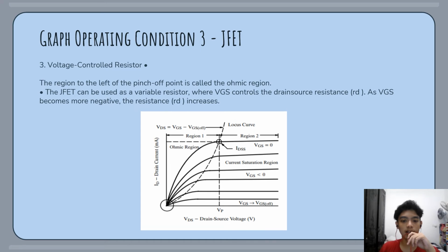Maximum drain-source current IDSS and minimum resistance RDS(on) will exist when the gate-source voltage is equal to 0 volts. If the gate voltage is increased negatively for an N-channel JFET and positively for a P-channel, the resistance will also increase. When the drain current is reduced to a point where the FET is no longer conductive, the maximum resistance is reached. The voltage at this point is referred to as the pinch-off or cut-off voltage and is symbolized by VGS equal to VGS(off). Thus, the device functions as a voltage controlled resistor.